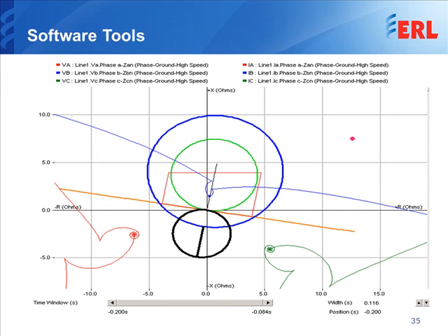What we have here is a line-to-ground fault, and the fault impedance for B phase is graphed there. We have also superimposed the line characteristics, or the Mho circles, for this particular line. So we have the RX diagram, the Mho circles, and the line impedance graph in this picture.